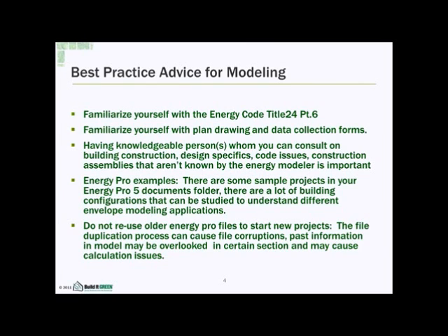And it's always a good idea to not reuse your old EnergyPro files as templates. I've seen that file duplication causes some errors and file corruptions, and past information always gets overlooked, and it causes certain loads, depending on if it's in a fan or heating or cooling or windows. I've seen it give calculation errors and cause buildings to not comply. So if you start from scratch, with a new file, it's always better, and just give yourself time to build out a full model.